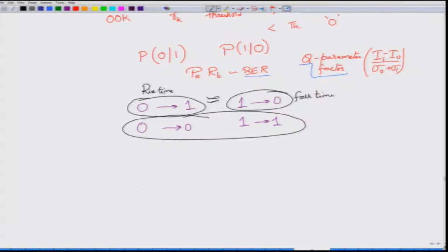What we do is we look for a 0 to 0 transition, where we take one bit boundary at the middle. So, this one is one symbol and this one is the next symbol. We take these two symbols and start overlapping the signals like this.